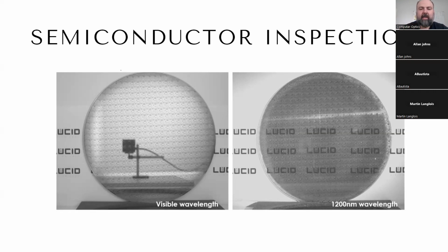So silicon absorbs visible and infrared wavelengths, making it ideal for most imaging detectors. But silicon can't be used for infrared detection because it loses sensitivity past 900 nanometers, and it's transparent to wavelengths longer than, say, 1100 nanometers. So this transparency to SWIR enables SWIR applications like photo emission failure analysis of ICs, or imaging of IC and MEMS layers for alignment errors.